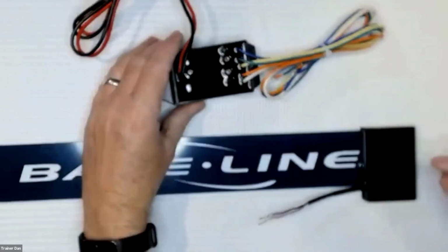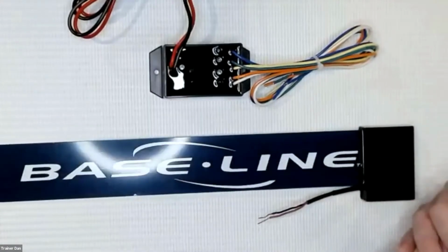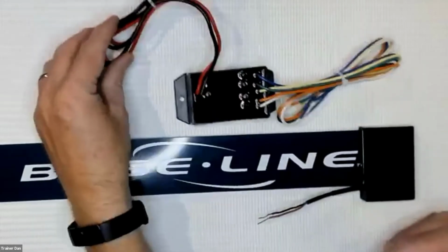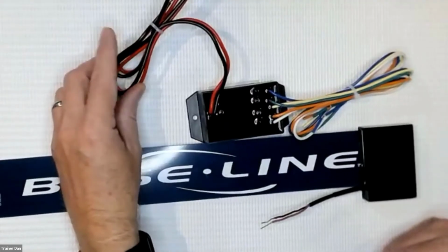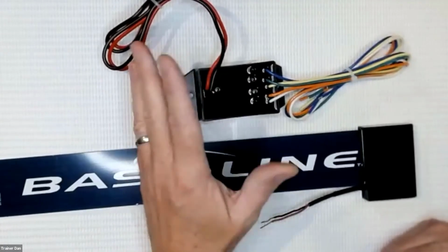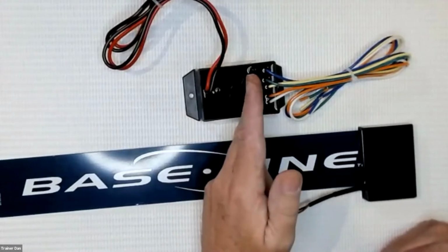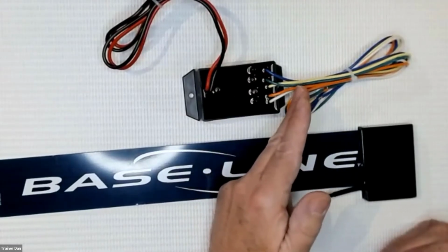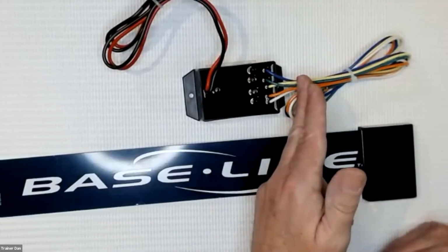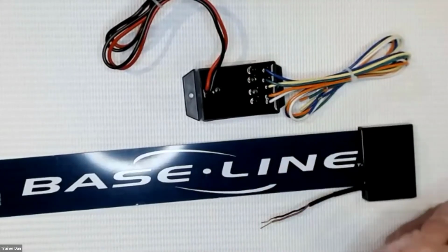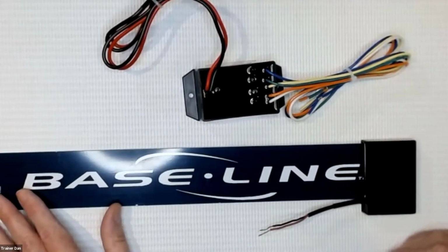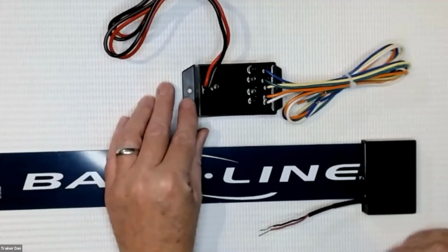So if the LED on the 2-wire side is blinking, what's that telling us? That's telling me that the 2-wire path all the way through to this side of the bicoder is good, that I have a connection through. It's able to communicate with it, but it may not be able to open a solenoid or activate it for some other reason. It could be a bicoder problem, or most likely it's a wiring problem on this side. Okay. So if that 2-wire side LED is blinking, is that telling us that we both have power and data communication?